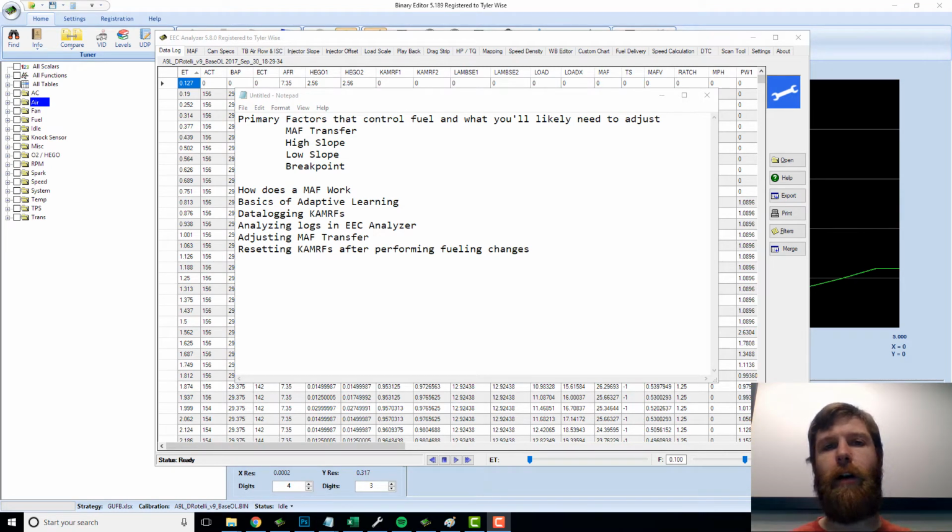Today's video is going to cover the basics of dialing in your fuel for your Fox Body Mustang using a Moates QuarterHorse, binary editor, and EEC Analyzer. And if you've been watching a lot of my videos so far, we've really been focused on how to change some different things in binary editor, but I don't think we've really even made a video yet where we've gone into EEC Analyzer to look at some data logs and figure out how that can be used to help us make some adjustments in our tune.